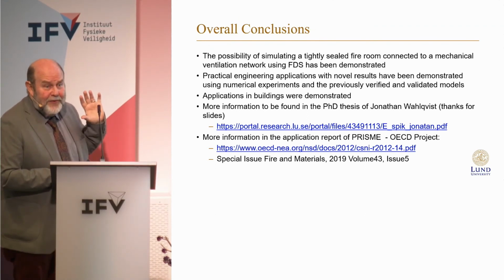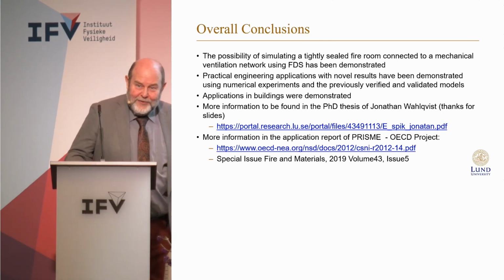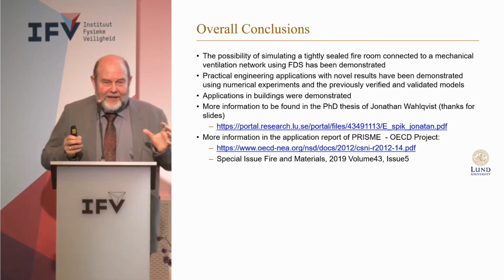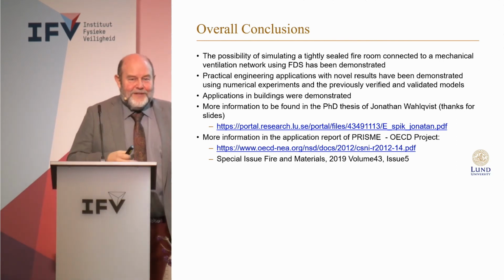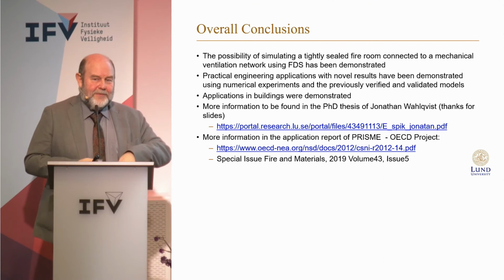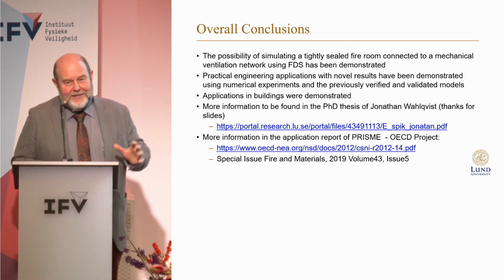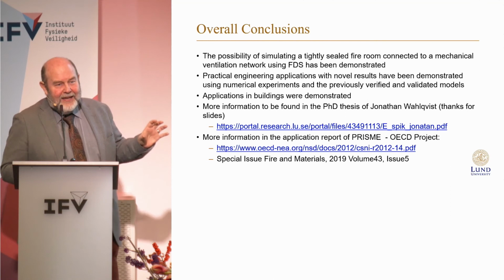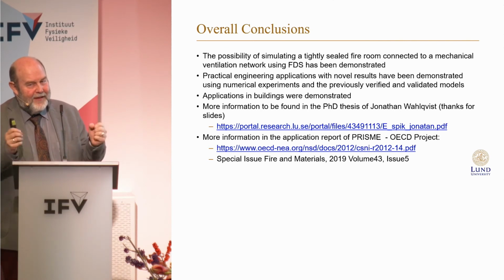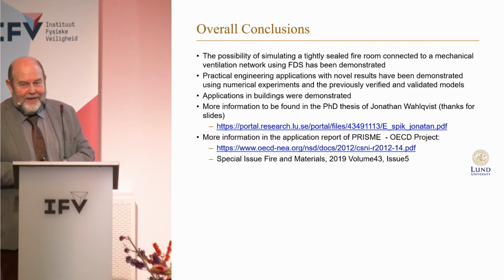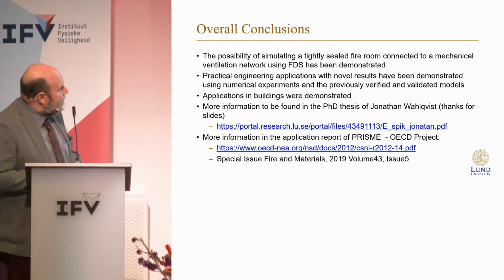If you want to read a lot more and also know the interaction, that means the increase, because I didn't talk about the fire itself. I only talked about the ventilation and the reduction of the ventilation and the oscillating behavior and probably the starving of the fire. But there's also, of course, an effect that the fire growth, we want to predict that, because what we do now in FDS, we put in this kind of fire which is in the open environment, and then hopefully FDS covers it through its models. But here, Jonathan worked also on trying to predict the so-called pool fire model. At least the alumni students should know the Babrauskas-Spiegler equations for pool fires. They are not valid anymore in this situation, so you cannot use them anymore.